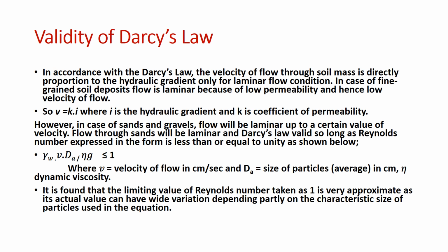Flow through sands will be laminar and Darcy's law valid so long as the Reynolds number, expressed in this form, is less than or equal to unity.